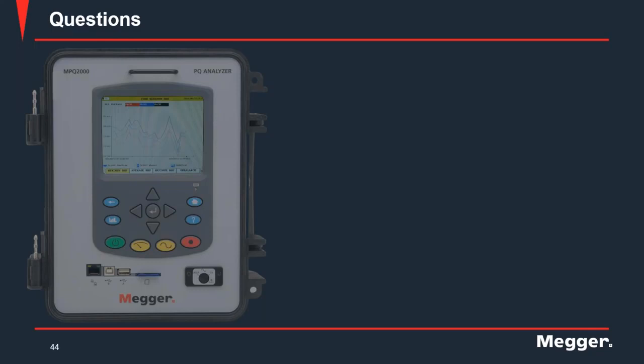And when we look at them, now it's coming down to analyzing that data. It's pretty simple to actually see what problems are causing something, okay? We can see when we have surges that are causing an issue. One of the things you want to do during that power quality study is that if you have a particular symptom that you notice occurs, just jot down the date and time that it happened, so that you can use this as a reference when you're analyzing the data in case it is a periodic surge that's causing the problem, okay?